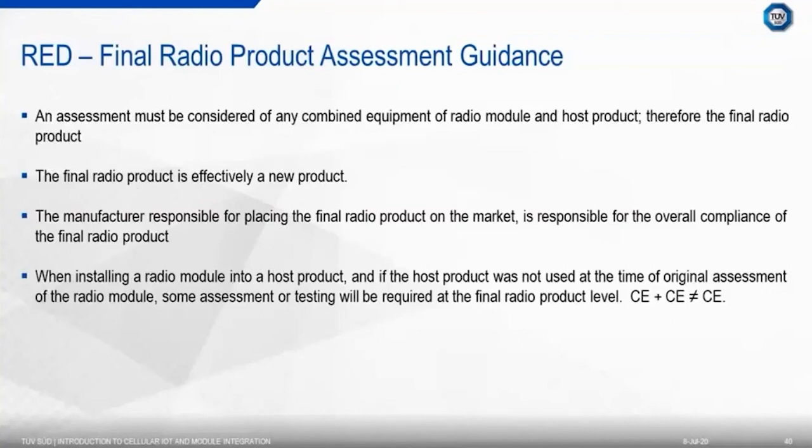A few times I have heard that an approved host now integrates an approved module, which means that the new final radio product is approved. That is certainly not the case, hence the comment there indicating that CE plus CE certainly doesn't necessarily mean the final product is compliant.